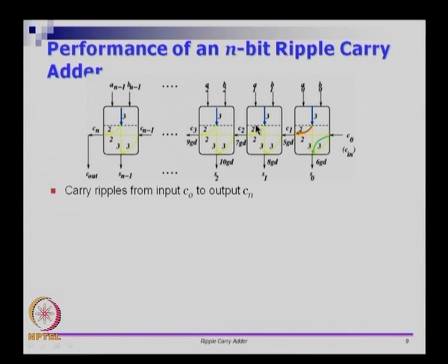units, this would have settled down at 3 units. So this is waiting, 5 units plus 2 units is 7 gate delays. At 7 gate delays, C2 will stabilize, C2 will not change anymore. So C2 is stabilizing at 7 units.